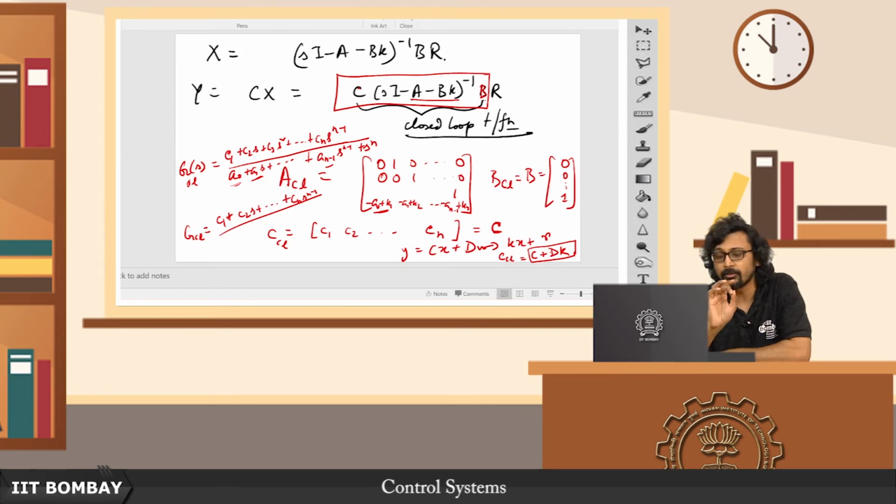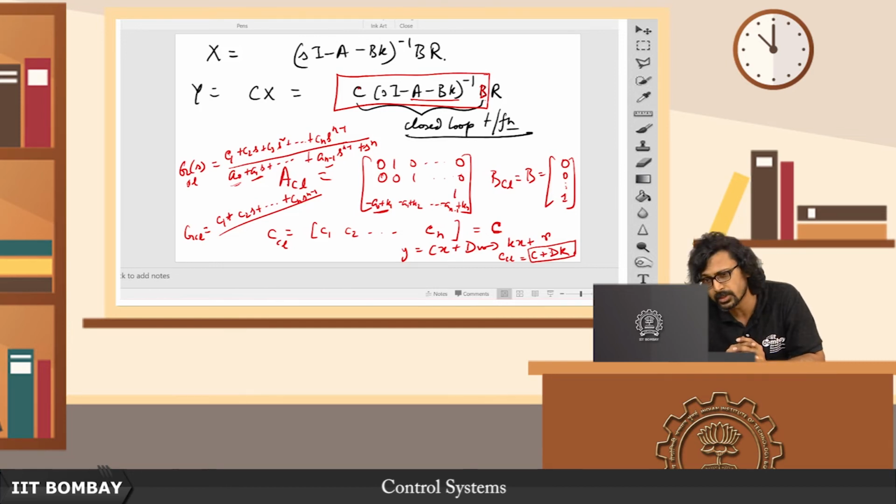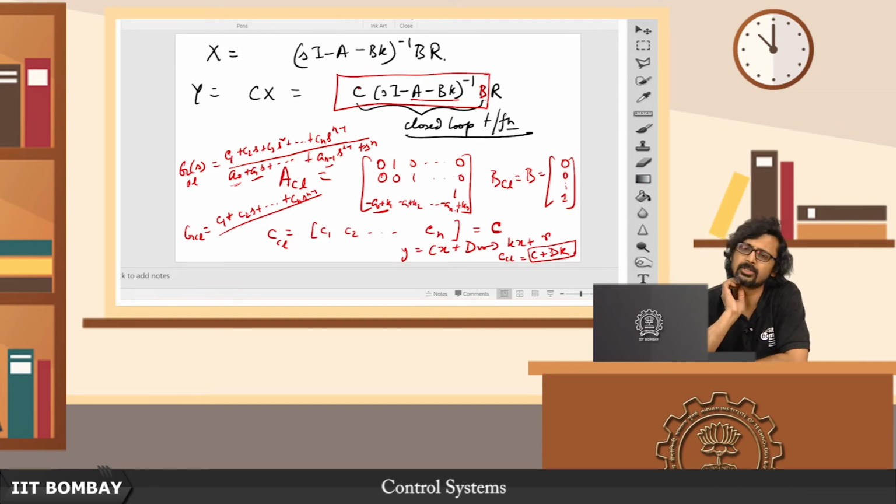So I want you to be aware that this is a limitation. Although things might seem like we have done quite a lot and achieved quite a lot, at the same time, even with this state feedback, with this observer and everything, you still aren't able to place the zeros. And why could the zeros potentially be a problem? When you have right half plane zeros, those are things we don't like. They are somewhat akin to time delays.